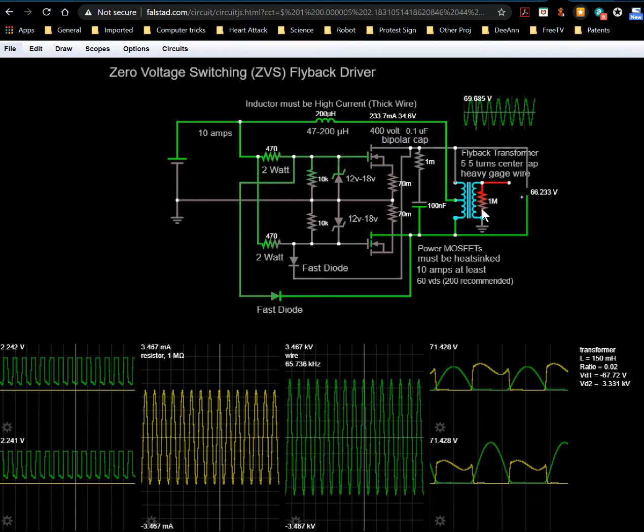That'll give you the resonant frequency, so you can plug that in and use a little bit of algebra: the resonant frequency equals 1 over 2 pi root LC. You can actually solve for L algebraically to find out what the ballpark of the inductance should be.